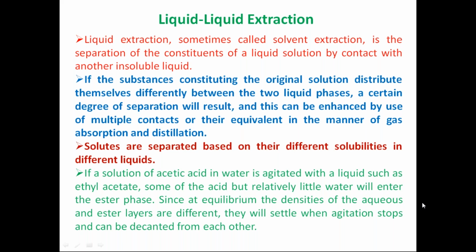Also we should look at the condenser as well as the reboiler. When you compare them as ancillary units for a distillation column, their capacities also should be very high because the alpha value is very close to 1. Therefore, instead of distillation, if you use liquid extraction for separating acetic acid from water, that will be more economically feasible.